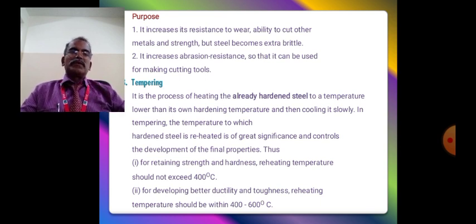And the third process, tempering. It is the process of heating the already hardened steel to a temperature lower than its own hardening temperature, and then cooling it slowly.